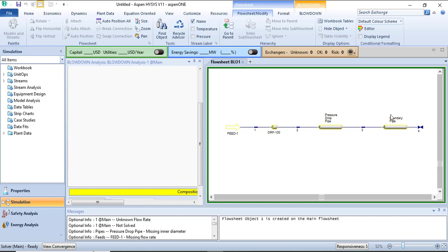So mostly what happens during the commissioning activities, after commissioning, the EPC contractor or the construction contractor fills the pipeline with nitrogen at about 3 to 5 bar pressure, and then what happens? The pipeline is pressurized from a bypass of the main isolation valve. It can be an isolation valve, it can be some kind of ESDV, it can be some kind of hand operated valve.